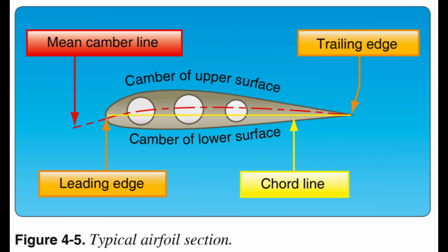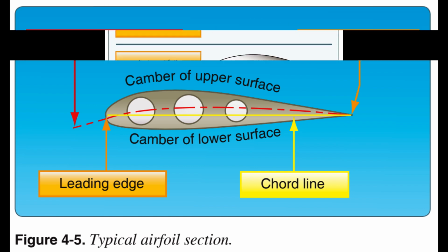Advancements in engineering have made it possible for today's high-speed jets to take advantage of the concave airfoil's high lift characteristics. Leading edge Krueger flaps and trailing edge Fowler flaps, when extended from the basic wing structure, literally change the airfoil shape into the classic concave form, thereby generating much greater lift during slow flight conditions.